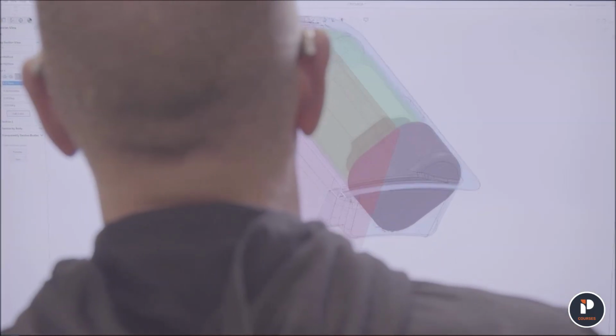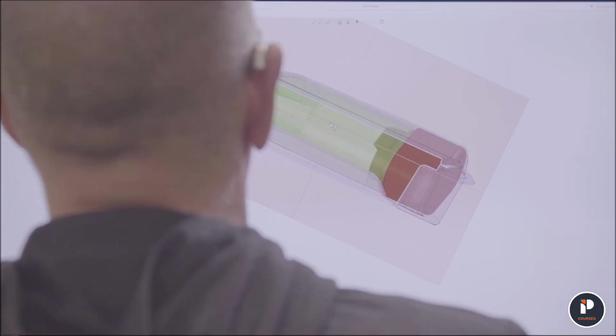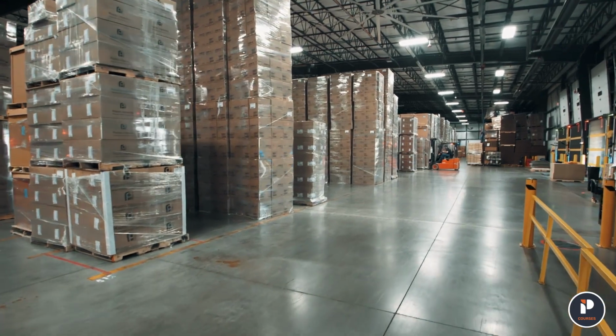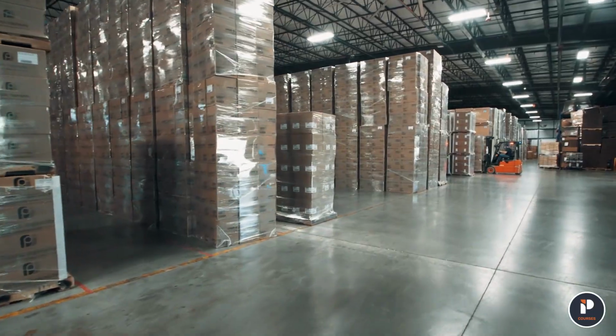Once a failure point is established, the engineer knows the lowest material gauge of the package they can use without it failing. To achieve what we call the optimal package design, we must minimize the material usage while ensuring the protection of the product. During the design process, it is important to inspect each design element of the package for potential reduction opportunities, such as evaluating material choices, tolerances, and other features that could impact the environmental footprint. Similarly, challenge testing can be done on secondary, tertiary, and distribution packaging to maximize pack-out efficiencies and pallet designs.